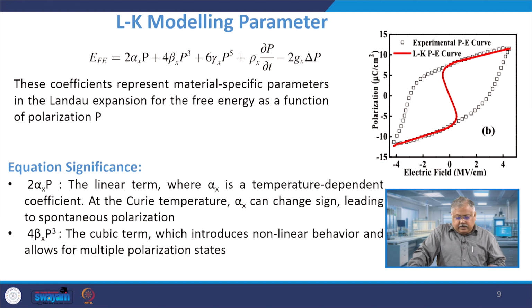Okay, there was a very interesting modeling done, and this is known as Landau modeling for the negative capacitance. This is where we enter into the modeling part rather than the device physics behind it. The Landau expression is given by this quantity. It looks complicated, but delta P is basically the change in the polarization, delta T is the time domain change, and gamma, beta, alpha, rho are all empirical constants, the Landau coefficients. Here is the variation of the free energy versus polarization. So if you change the polarization, how does the free energy change?